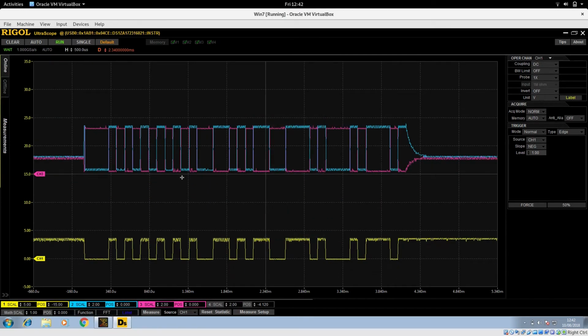That's RS485. Now there's a few others, RS422, but that was the start of this differential signaling, and I thought I'd better mention it when I was leading from RS232 and strict serial, where you've got just one line transmit, one line receive, to this differential signal, because most protocols now that we're going to look at are going to use this differential signaling in one form or another.